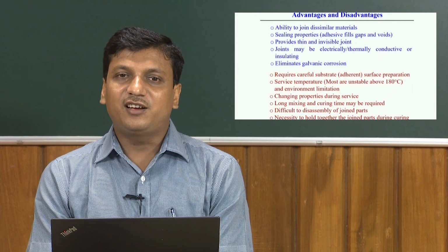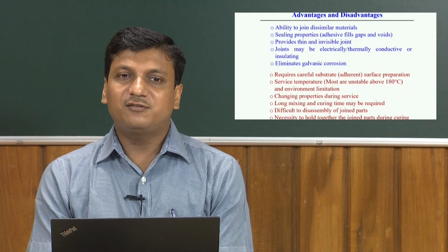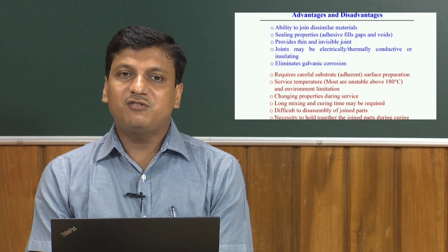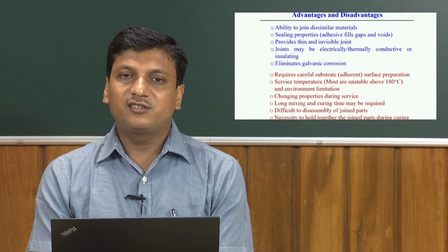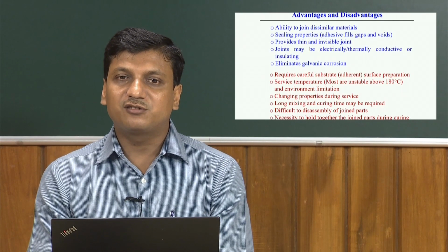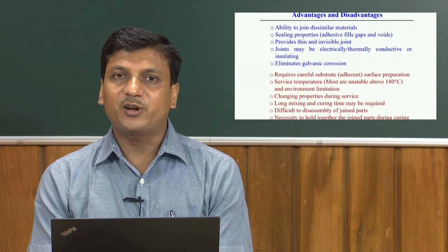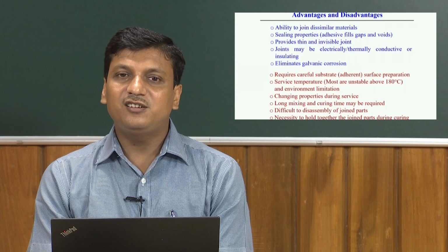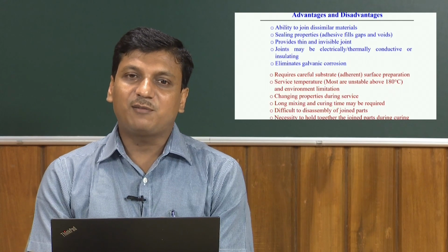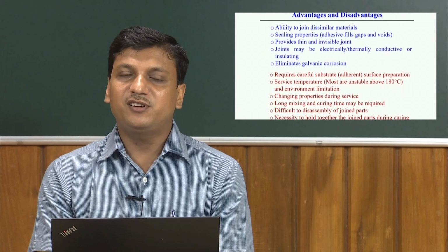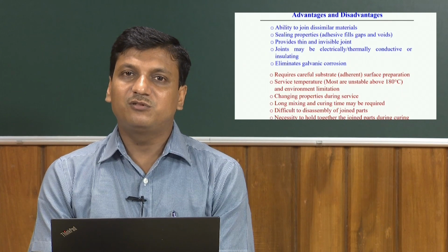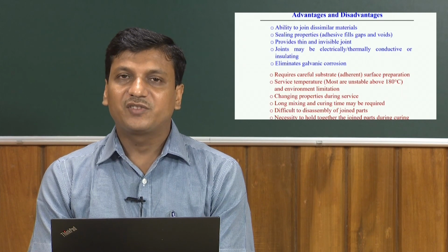the disadvantage of this adhesive bonding, the first is that it requires careful substrate surface preparation. So, surface preparation is one important factor. One is the cleanliness and the roughness. These two are the important parameters for a successful joint using adhesive bonding.